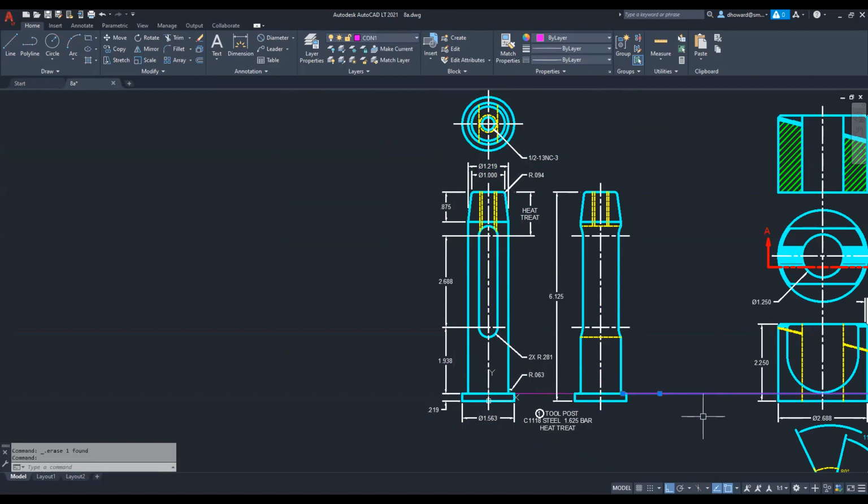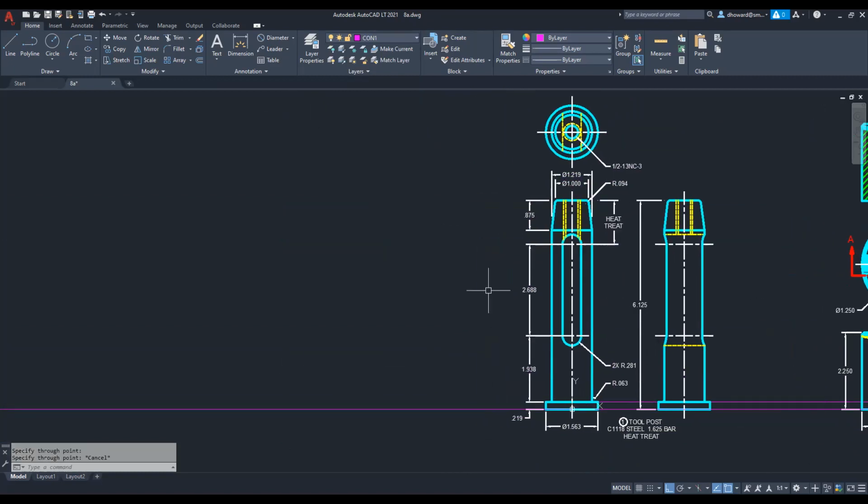And we'll start off with a horizontal construction line at the bottom. And I'll line it up with this other view here so that makes sense. Okay, so you can see right off my drawing the offsets. I've converted them into decimal. Of course, on the original drawing, they're fractional. This first offset is 7/32, for example, or you can type in 0.219.